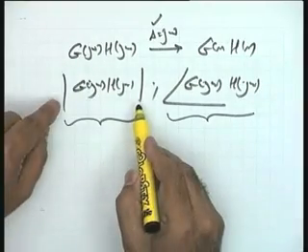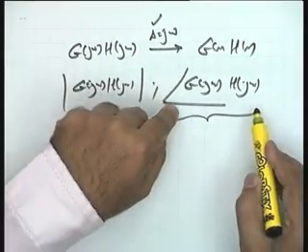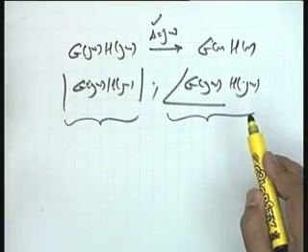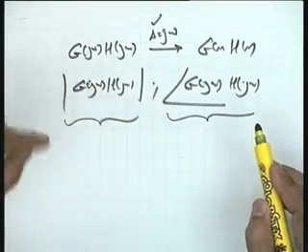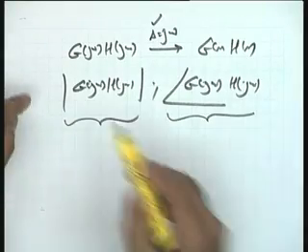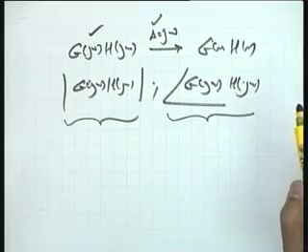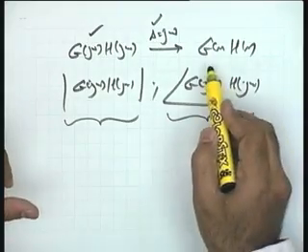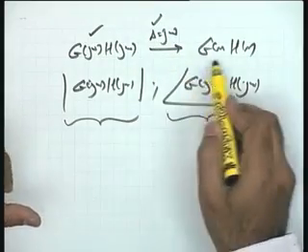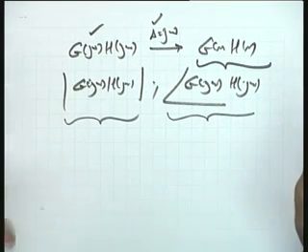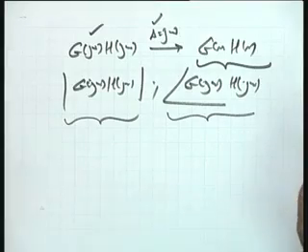So when I know this magnitude and this angle for any value of frequency, naturally I know the output of the system when subjected to a sinusoidal input. So you see, I can say that G(jω)H(jω), which as per the Nyquist criterion is the mapping of the imaginary axis under the mapping function G(s)H(s), equivalently speaking is nothing but the frequency response of the open loop system.